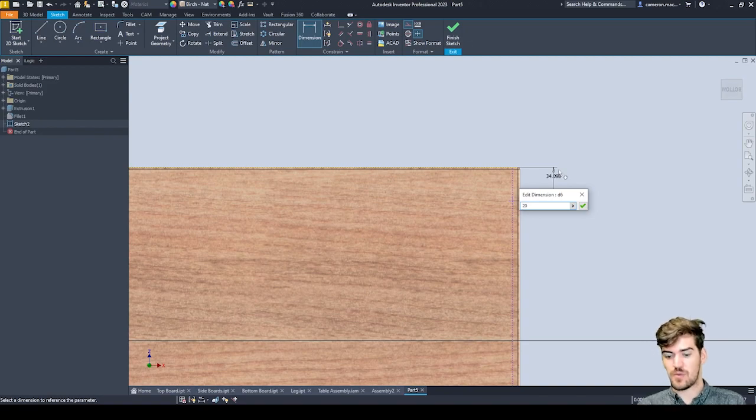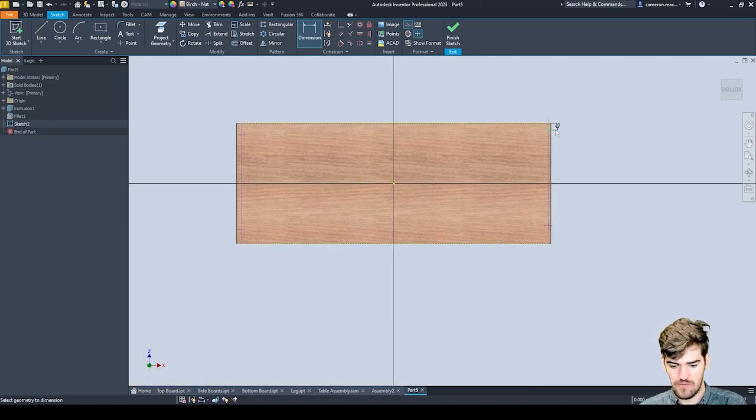And if we wanted to be clever with this, we've got the ability to come in and say this is going to be the whole offset in the dimension, in the depth, and that's going to be equal to 20 millimeters. So that's something we can again pick up later on if that was something we wanted to grab from within our parameters. So all I need to do now is define the other values as equal to that one by selecting it, and you can see all of the other points are going to be driven by the original item. Not only that, but we'll be able to reference that for all of the other holes, so they've all got the same placement later on.